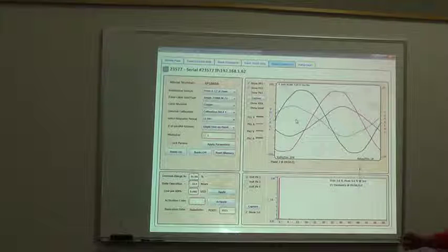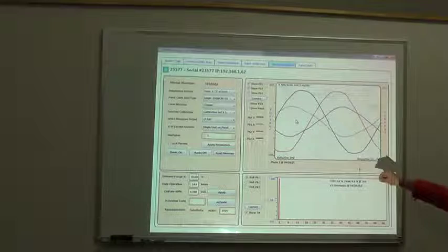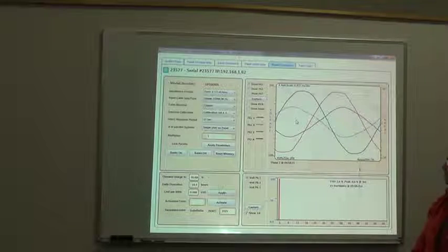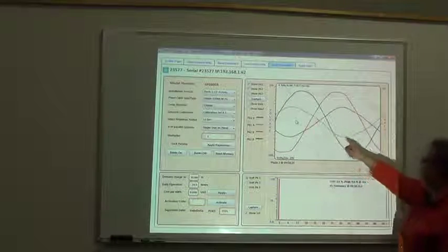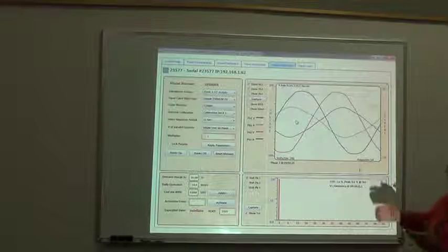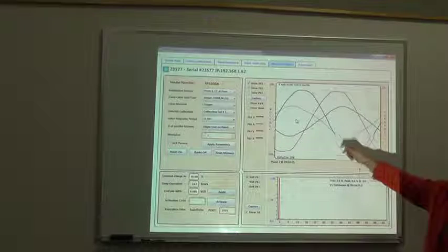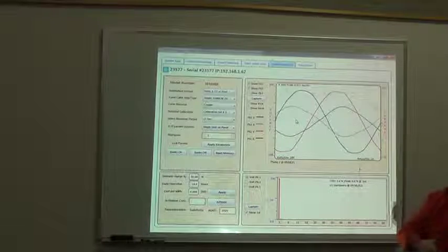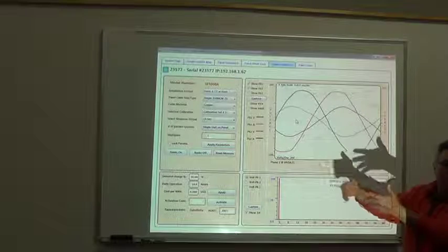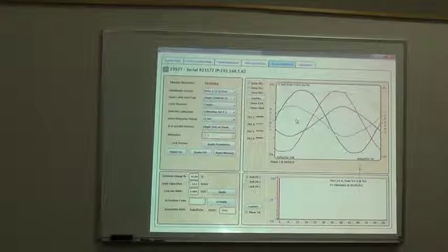There's a power factor issue, but it's lagging, which it's supposed to be. What I don't expect is the current for phase 3 to be in place of the current for phase 2. I expect the current for phase 2 to be roughly around the voltage for phase 2. But when I see that the current for phase 3 is showing up where I expect the current for phase 2 to be, then it just means that the wires are twisted. Crossed. The wires are crossed.